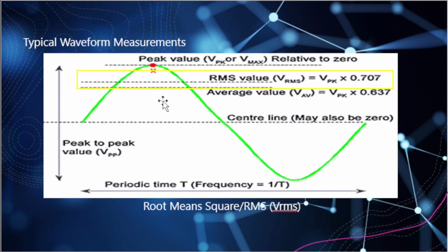However, depending on the tools you're using, you may only be capable of measuring volts peak-to-peak or volts RMS. In general application, if I am using an oscope, I can get my peak-to-peak measurement and my peak measurement, and then from there, use these formulas to calculate out my volts RMS or volts average.